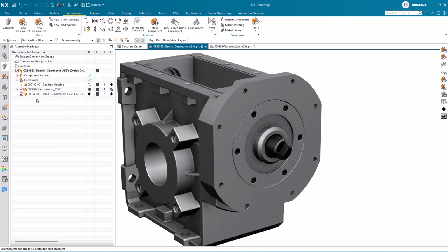Awesome! As this was the final piece in this demonstration, I would like to summarize what you have seen. You have seen how to create a new assembly file using the proper template while creating an assembly. This is important as the assembly template contains important settings for an optimized behavior of your assembly in NX. We utilized a folder set up as a palette, where you can utilize the drag and drop procedure to easily add components to an assembly.